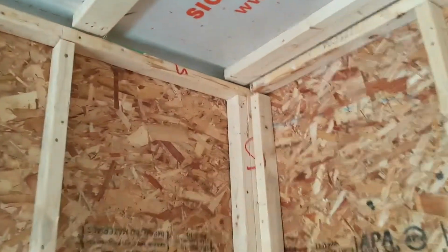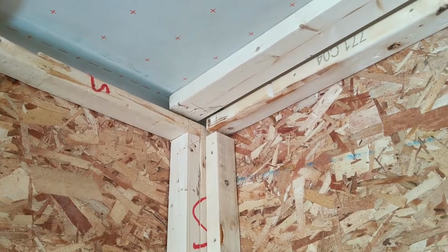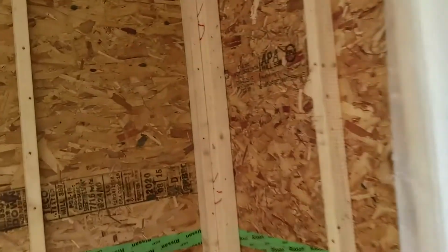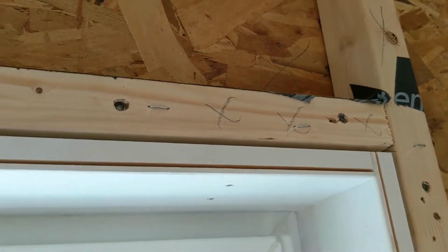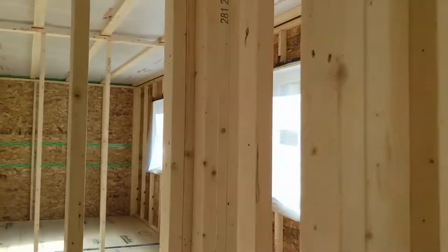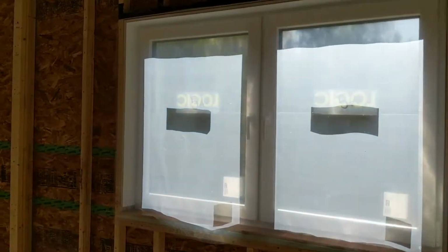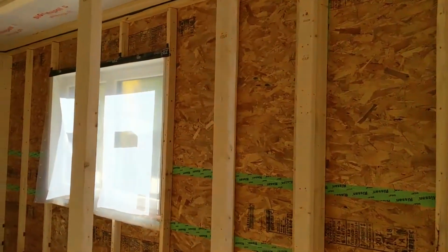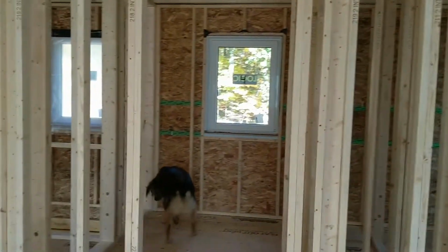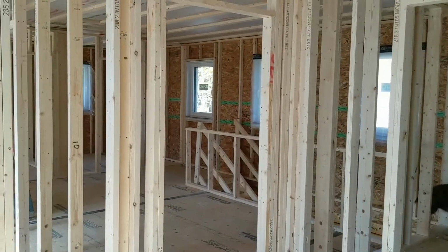This corner here maybe could use a little bit of reinforcing with some foam. Didn't find anything at any of the windows. This corner here could use a little bit. Maybe just a little more tape up here on top of this corner of this RO, for some reason, felt a little there. But that's basically it. I couldn't detect any air leaks using the back of my hand, which, as I've said, is pretty sensitive. So that's all good. That bodes well for the blower door test. Now we just got to get that manometer to work.